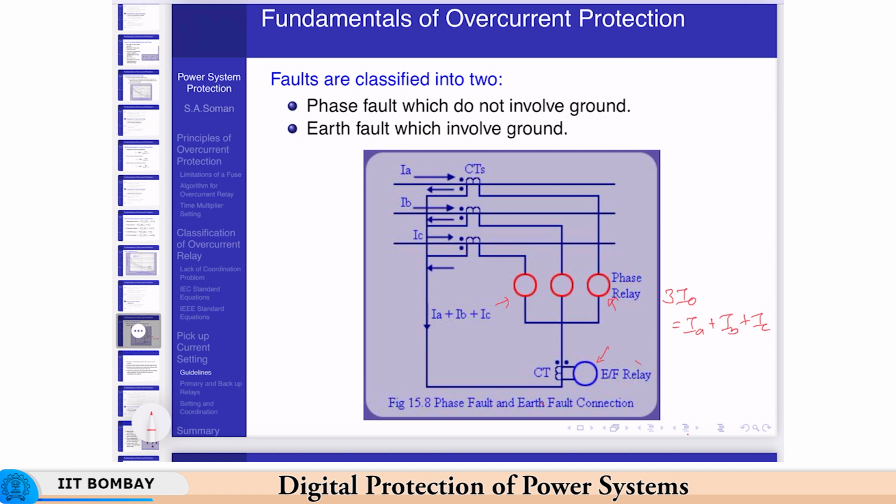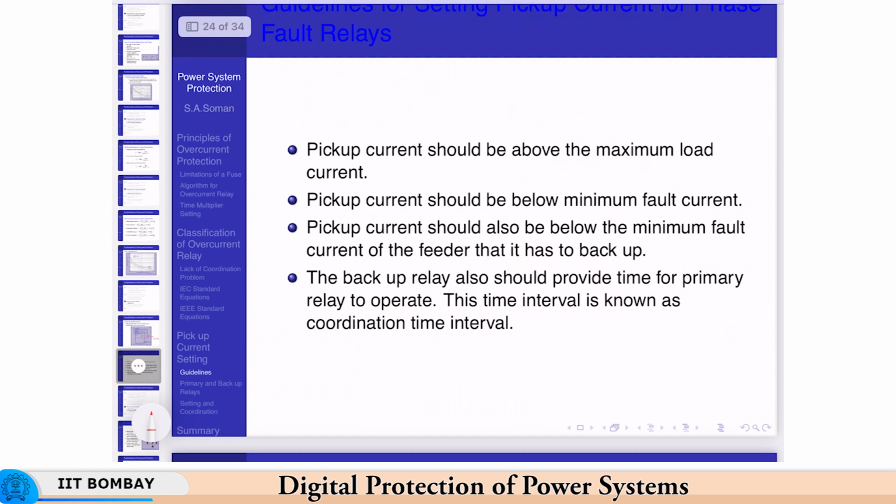So, you may not require the earth fault relay as a separate relay. It may still be provided, because it provides a backup function and avoids a single point of failure. That is a matter of reliability, but as a relay function, it is strictly not required.